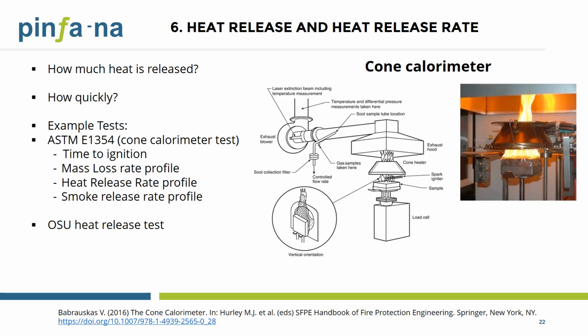The cone calorimeter test per ASTM E1354 standard is a bench scale test that is commonly used to quantify the heat release profile of a combustible material. Only a small sample with a 4-inch by 4-inch dimension is needed, mounted in a horizontal orientation, typically under a given heat flux from a cone-shaped heater in the test.